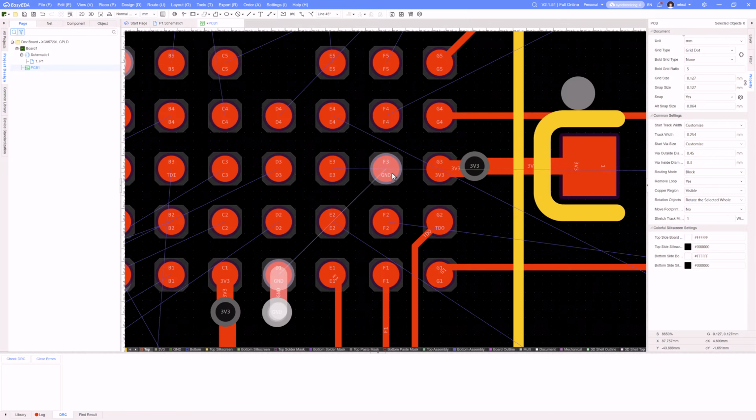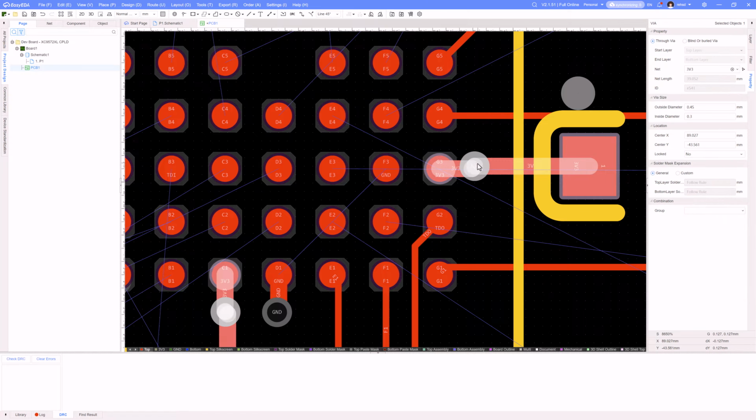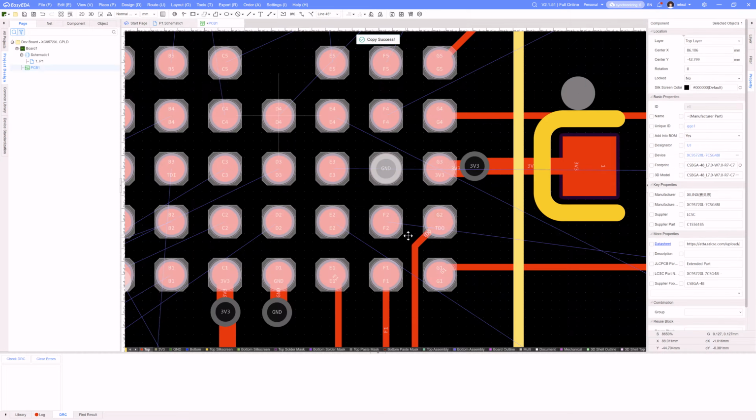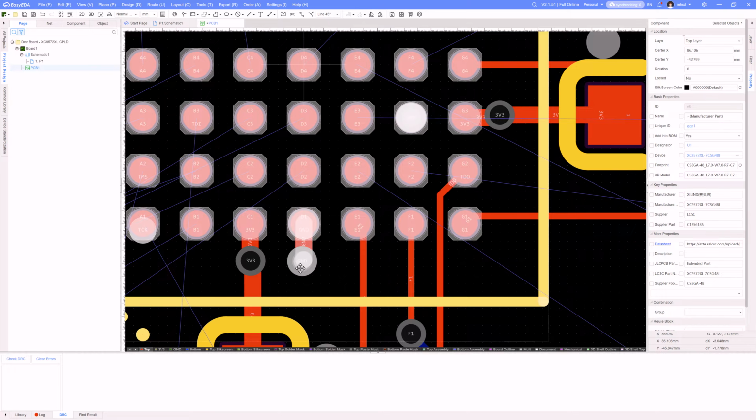So I have some choices here. I can either try to run a little ground signal out here so that I can get space for one of these vias, or I can go with a smaller via. I think the other thing I can do is I can just put a via right on it, and I'm good to go there then. So that basically is going to put the via right in pad. Now I could do the same thing over here, of course, if I wanted to, but I'm going to do that with a via pad. I'll run these two out.